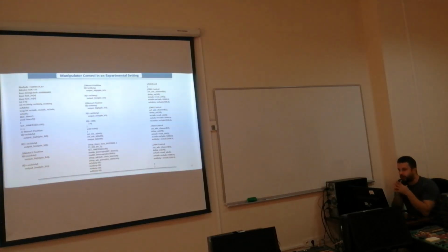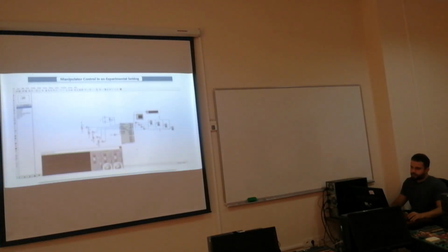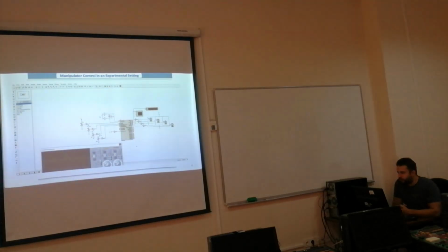Then in the while loop, we are using analog digital conversion functions to get the duty cycles between 1 millisecond to 2 milliseconds. Also, we can see the 200 value to get the desired 20 millisecond PWM signals. Now, we first will perform the simulation application, and then we proceed to the experimental implementation on the hardware.